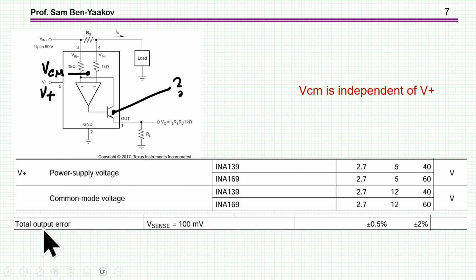Now the error specified by the manufacturer is a maximum of 2%. This is not very good because there are many applications in which you'd like to have a high precision measurement. Well, in many applications, I should also say, 2% will be okay. So in this 2%, you can actually absorb the error of this collector and emitter current difference, which is like I've said 0.5%, 1%. So this takes into account all of these. So this could be a regular transistor, although we really don't know what it is.